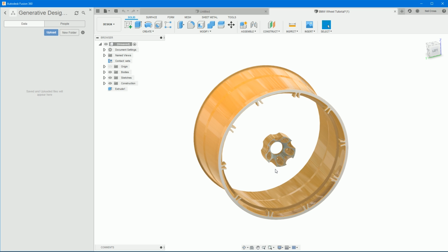You want to minimize the mass, maximize the stiffness of the part, and then it will sort of organically grow material out between the regions that you've given it, and then it gives you this fancy shape which conforms to your design parameters. It conforms to the structural properties that you've told it to.